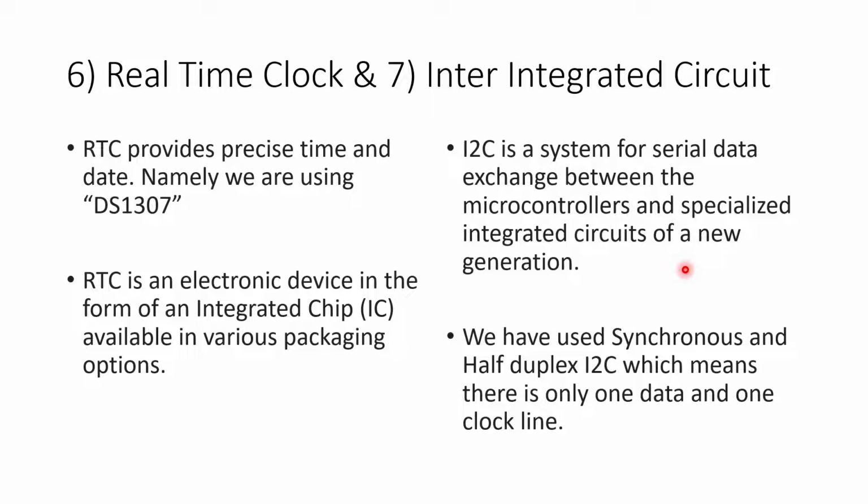In our case, we are using such a specialized integrated circuit, RTC, and our microcontroller is PIC16F877A. We are having synchronous and half duplex I2C, which means there is only one clock line and one data line present.